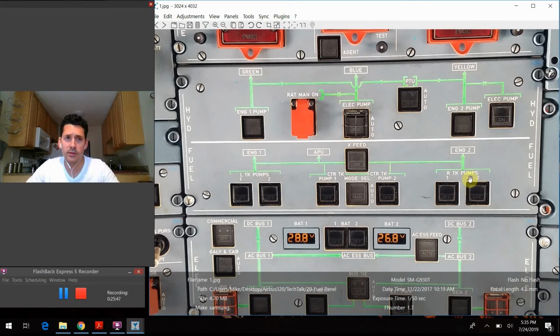Now when we read the checklist, part of doing that is verifying that we've actually got the fuel on board that the dispatcher had planned. So it's just a verification step in the process, a little mental device. A lot of guys won't actually turn the pumps on until we've actually got the fuel in the airplane. This is a really smart idea. It's just one more little reminder that we can use to keep ourselves honest and make sure we're not departing without the right fuel.